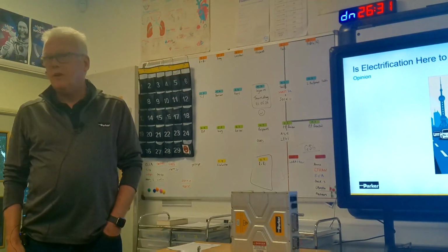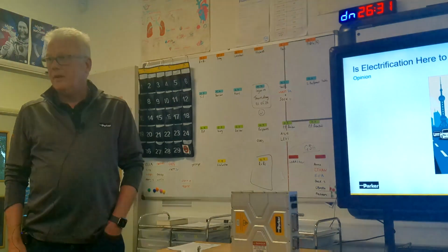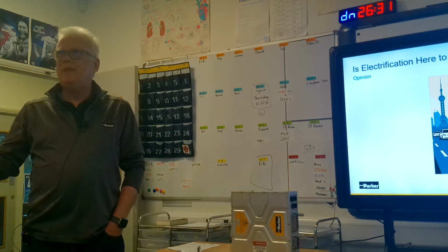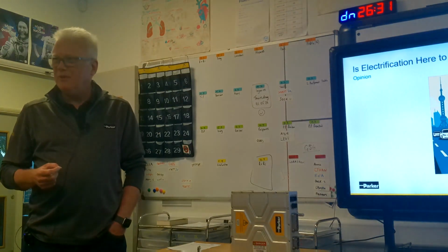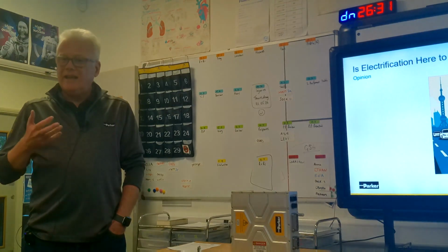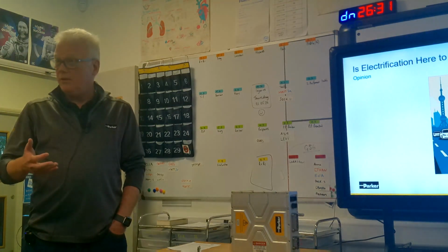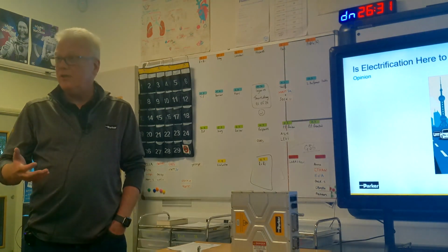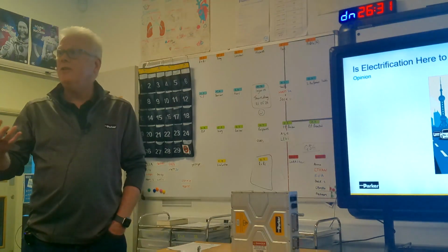Right, and you don't need any special inverter to do it, do you? No. The flyback diodes? Well, the flyback diodes are part of it, but they're really there for the switching. Once you've got a grip of current, that's one of the first things my first technical director drilled into me when I started working on electrical machines. Get control of the current, because once you've got control of that, you can control torque and make it do what you want. You can do motoring, you can do regenerating.